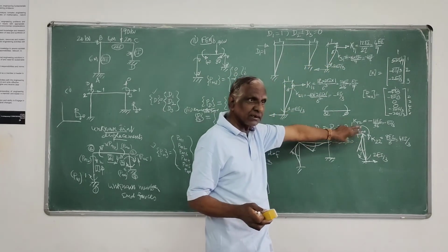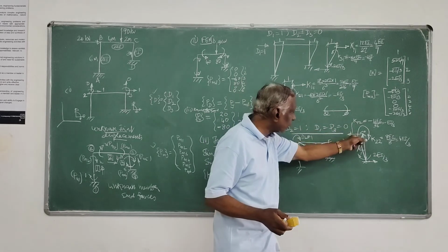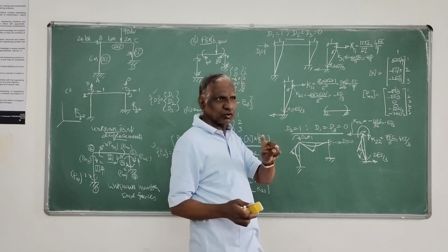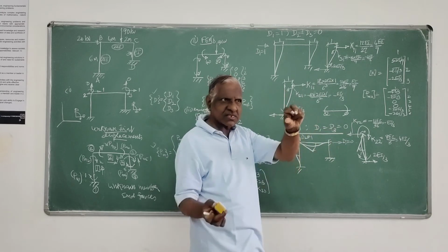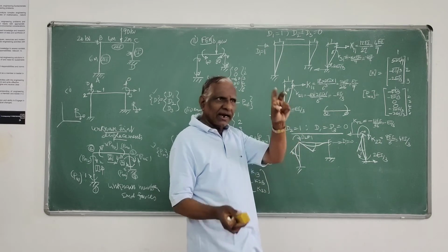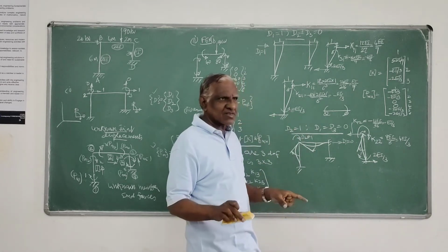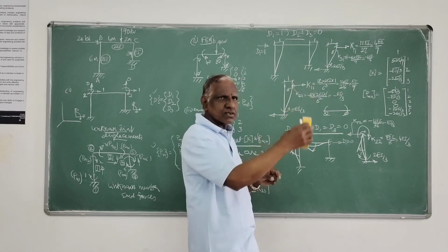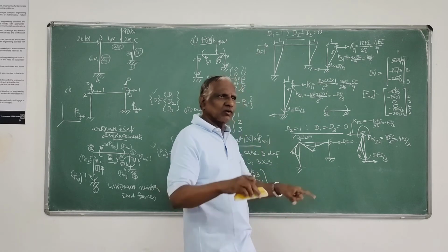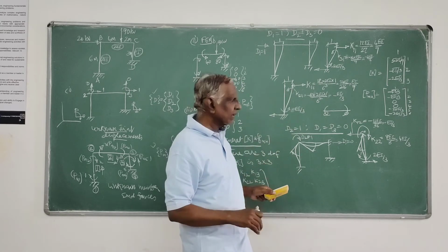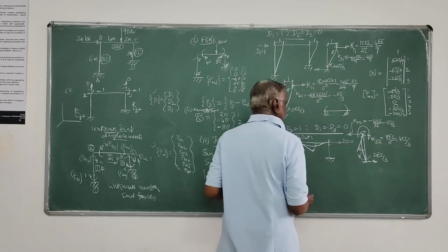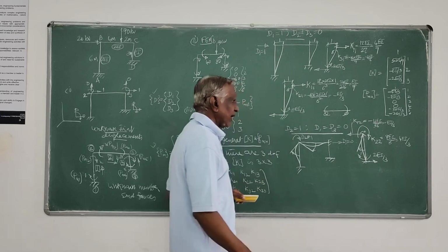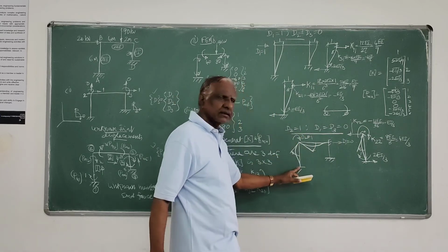But here it is displacement generate, that is the force generated on account of rotation. So it is 6EI by L square. So that you have to be careful. 4EI by L, 2EI by L is unit rotation moments, and shear is 6EI by L square. Whereas displacement, sway, that is displacement direction force is 12EI by L cube, and rotation will be 6EI by L square. So this is 4EI by 3, 2EI by 3, this is 6EI by L square. These are the moments in this.